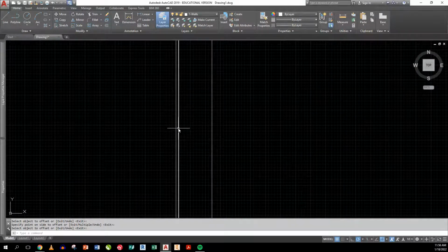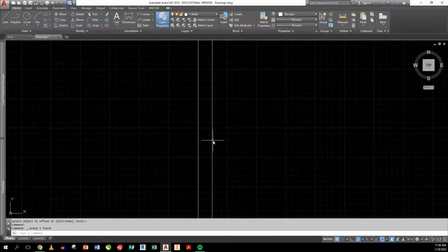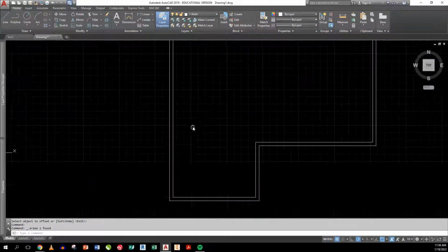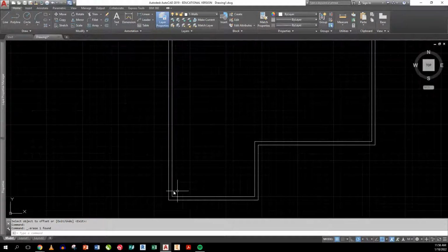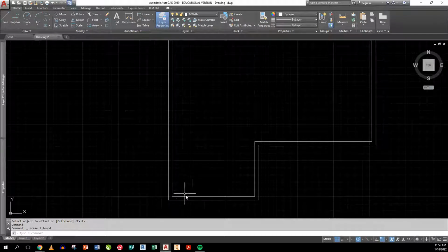And that's the reason I don't actually do this inner line usually too, because the framers know to put the skin on the outside, but the drywall folks are going to put the drywall on whatever's standing on the inside, and the framers need to know where those corners are. So I usually go to the corners so they can just nail the studs right at the corners, and I usually make a note of that.